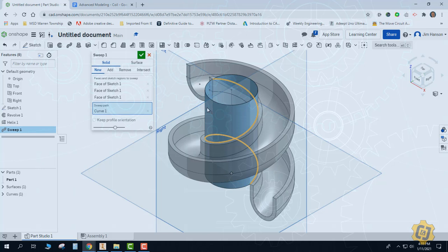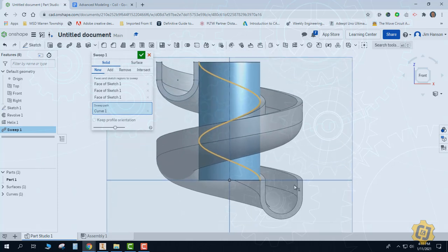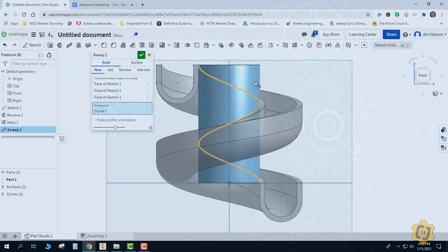Now, just as we said earlier, even though I've gone ahead and designed this slide right at the top of my cylinder or my full height, it has gone ahead and traveled down an additional slide down across the bottom. If that's not what you want, you have 2 options. I could have either changed the height of the cylinder itself to match up what I wanted, or I would have had to go into the helix and do some math to try to figure out how to get this to actually land where I wanted, to either decrease the pitch or height, either one.